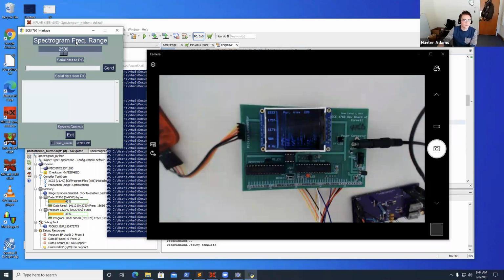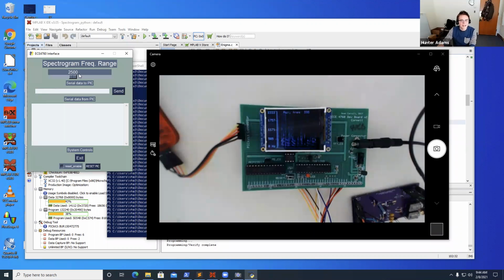This is a relatively simple user interface, but what it allows you to do, as I slide this, if you keep an eye on the Y axis here, is change the scale of your spectrogram. So if you want to look at the spectrogram, for example, of birdsong, which tends to be higher frequencies, you may want to change the range so that you can see those frequencies. Or if you're looking at whale calls, which tend to be lower frequencies, you may want to change the range of your spectrogram so that you can see more details.